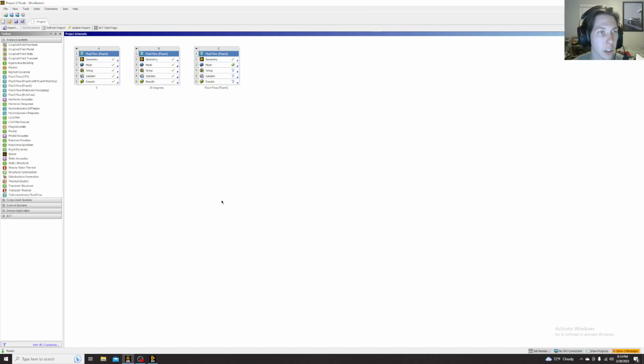Hello, welcome back. This is going to be a simulation on the flow of an inclined flat plate, and I'm going to be doing 30 degrees for today. So first you'll open up your Fluid Flow Fluent, drag that over, and then once you have that open, you just can click on geometry.